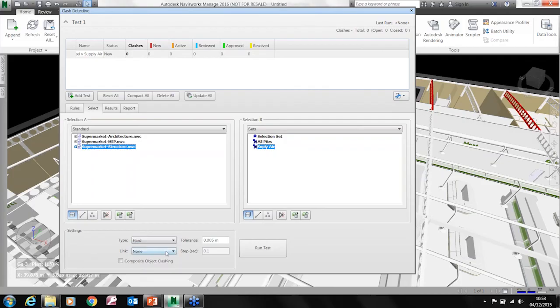Okay. I can also link it to the Timeliner. So imagine that I've got a tall building going up and I've got some site equipment. So I've got maybe a tower crane hanging over the building. At which point does that tower crane get in the way, need to be moved? I can actually then calculate the exact time within the project plan that the clash occurs as well.